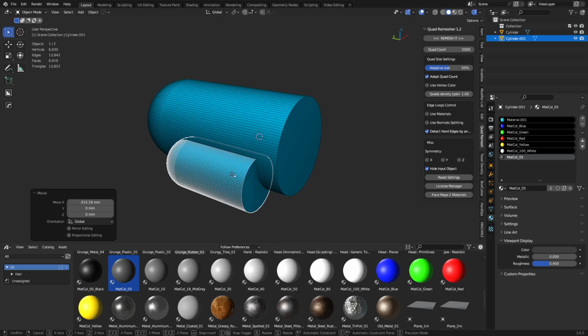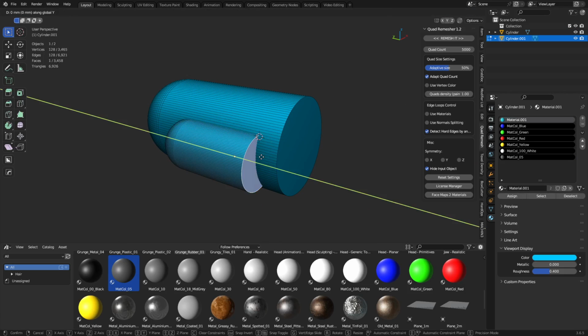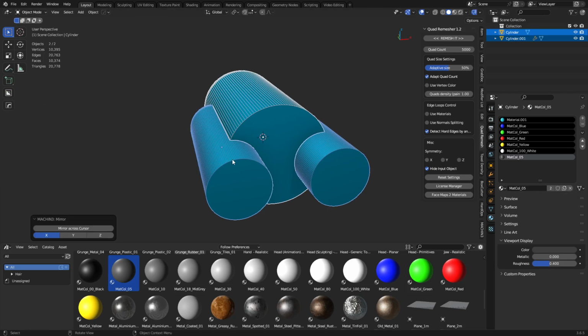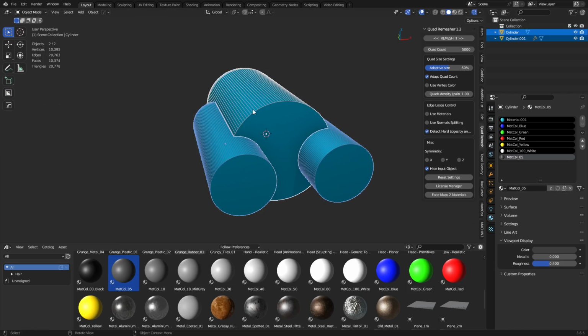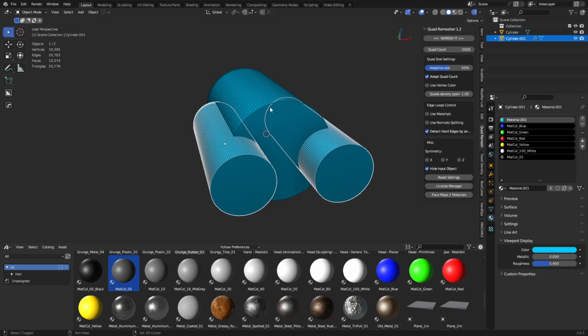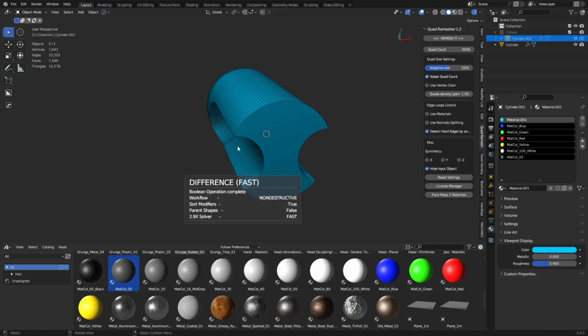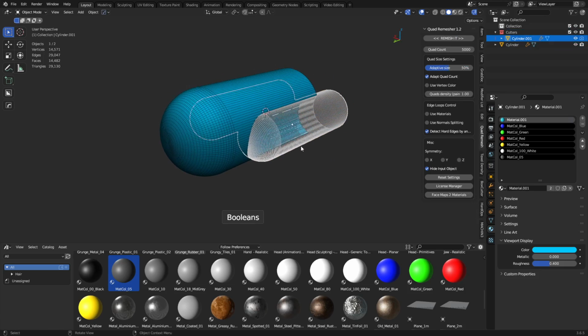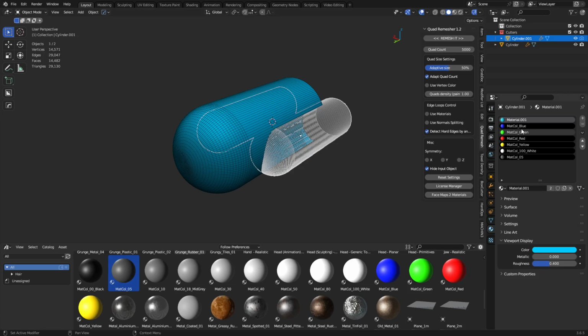So you can start doing the Boolean Ngon workflow very comfortably this way. You can mirror things across using machine tools. This isn't meant to be a modeling video, but we're going to go ahead and grab this, do a Boolean subtraction. We have something like this going on, right? So Q, E, bring that cutter back with Hard Ops, if you're using Hard Ops.